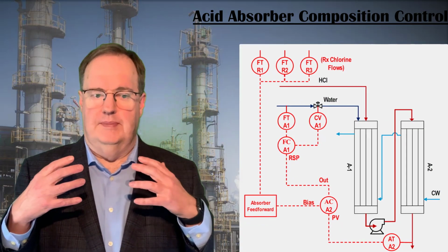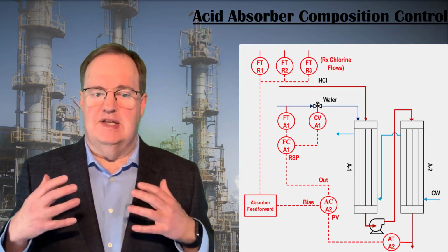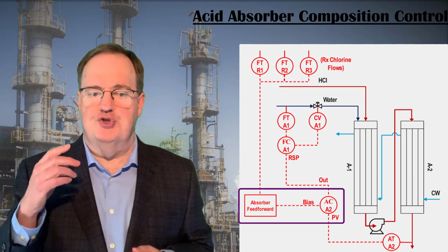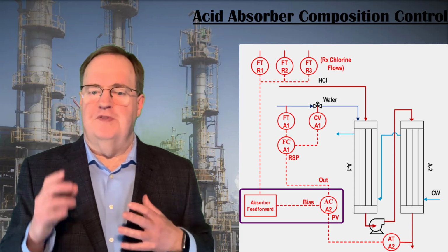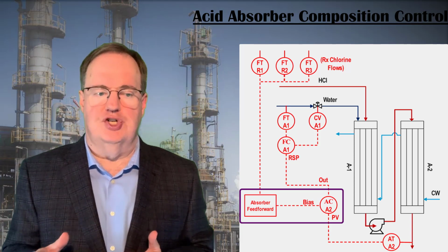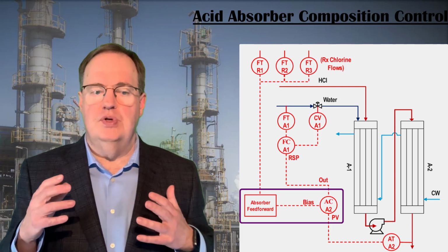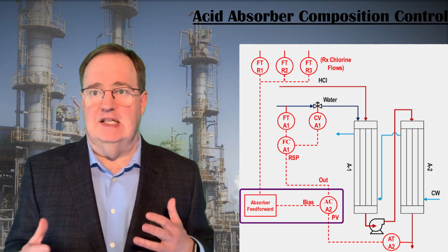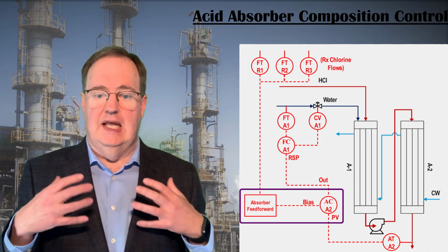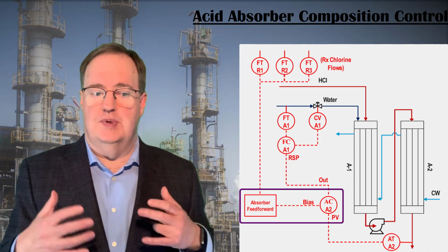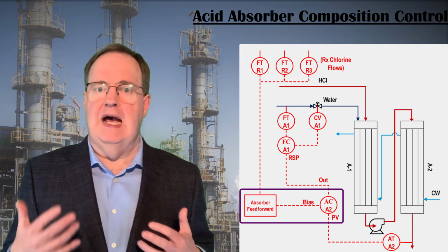When we take this model and add it as a bias to the supervisory acid control loop, all but the fine-tuning of composition will be achieved through use of the model. And if anything, the water flow adjustments will anticipate, rather than lag by minutes, disturbances to the HCl flow and acid strength.